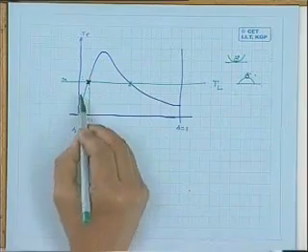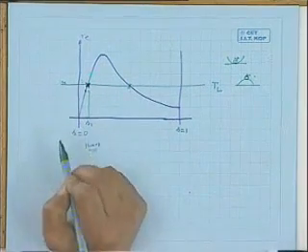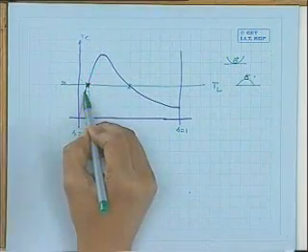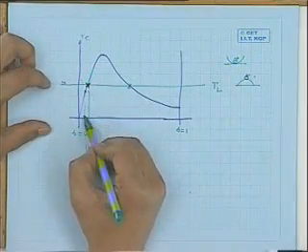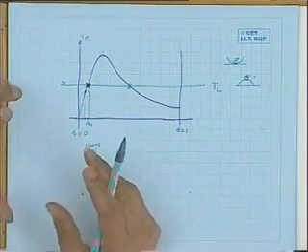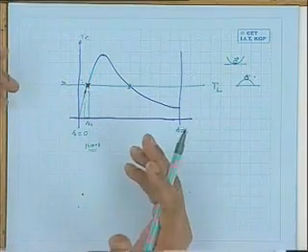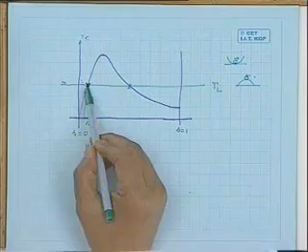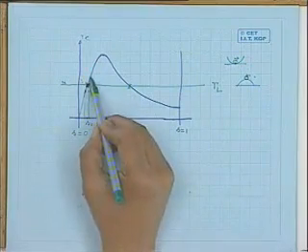Then what will happen? What will be the slip value? Slip will become further less. That is, here the operating point will shift. The moment it shifts here, you find the electromagnetic torque developed is this much, but the load torque is more. Then what will happen? The machine will try to once again decelerate and finally come here.